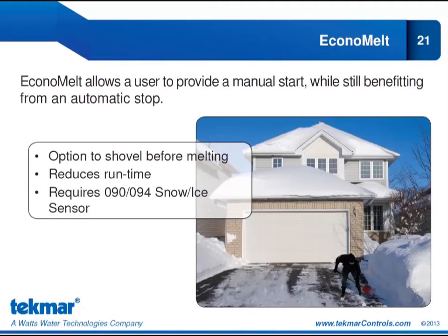So after we finish shoveling, we can manually start our snow melt system at the SnowMelt Control 654 and still benefit from the automatic stop of the snow ice sensor 090 or 094. So we will have a very short runtime of our snow melt system because we've used mechanical means to remove as much snow as possible.